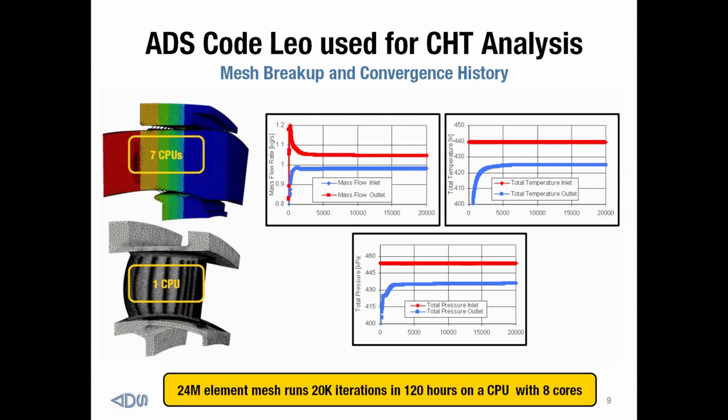But you have to remember that we're injecting cooling flow into the domain. So there's going to be some imbalance. And for this configuration, we expected somewhere around 6.5% cooling flow, and that's roughly what you're seeing here. So we were pretty happy that we at least got a reasonable answer for first try.